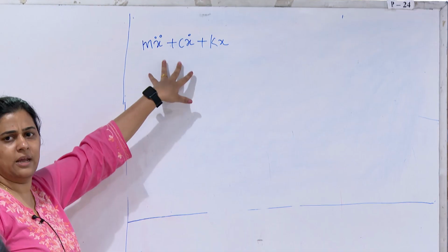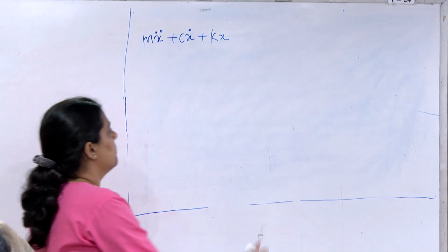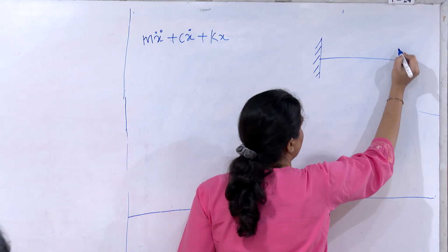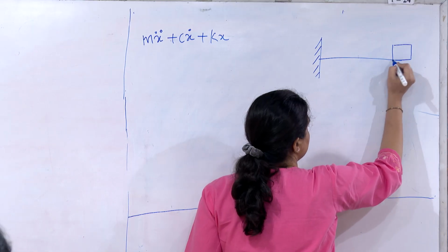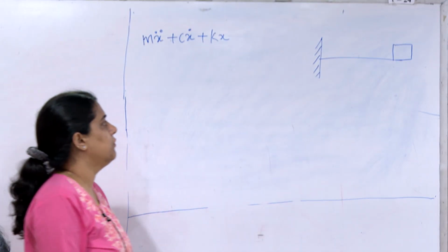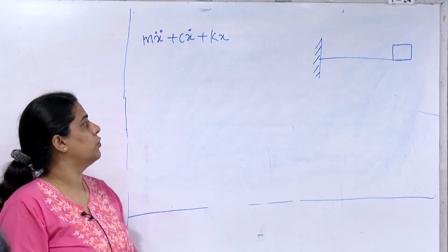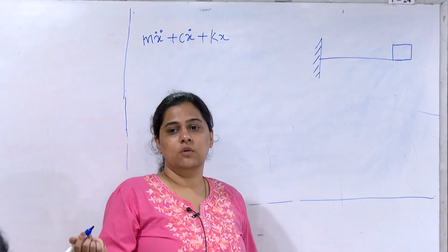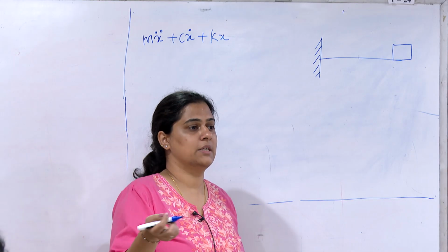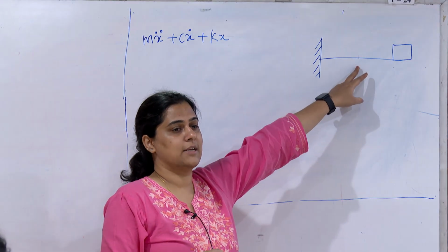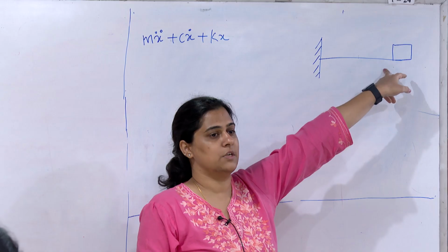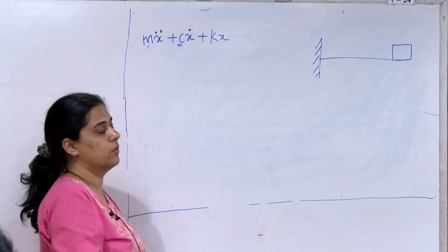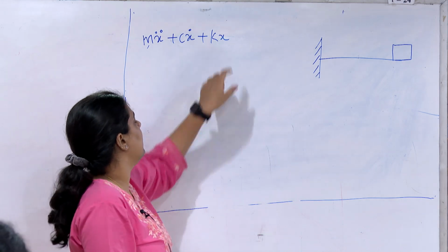It will have the same governing non-linear terms. This I think everyone knows, spring mass damper. Suppose you have a cantilever beam with some tip mass. If you are from a mechanical background, you would know how to find the equivalent stiffness of a continuous beam. You will have bending equations, and with the help of the maximum deformation, you can find the equivalent stiffness of the beam. So this term can be found out. Likewise, equivalent mass can also be found out.